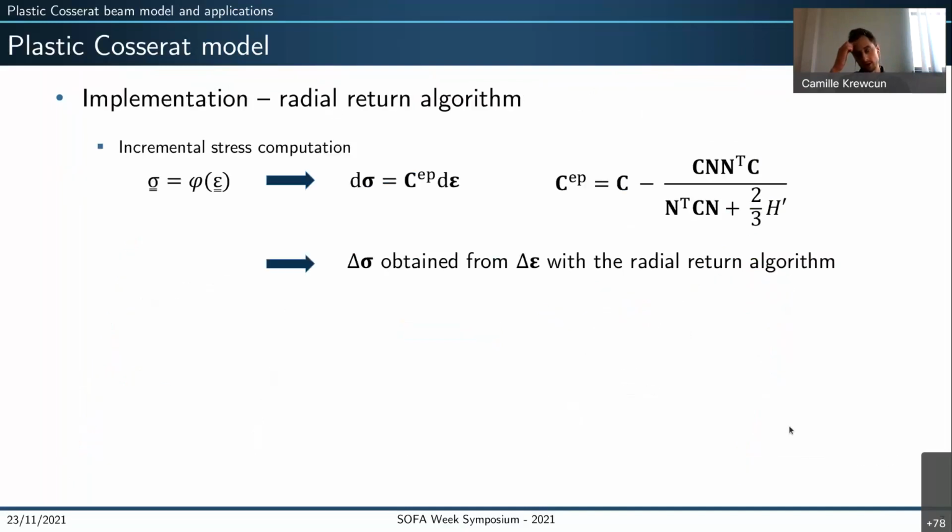So very briefly, usually when using elasticity, the relation between stress and strain is explicitly expressed in the computation, thanks to the generalized Hooke's law. But in plasticity, this relation becomes nonlinear. Actually, we don't use an explicit representation of the relation, but rather we switch to an incremental solution of the equations, allowing at each time step to compute a linearization of the behavior law, so plastic linearization of the behavior law. And this allows us to compute an increment of stress from the current increment of strain.